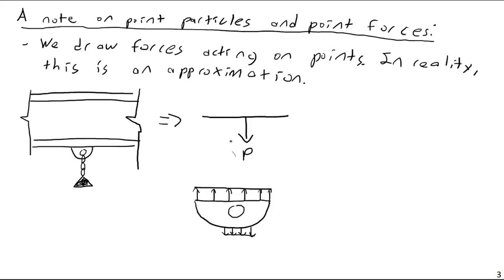So again, this is just a model. It's a useful model. Point loads are fine. Point objects actually work just fine for many applications. But I do want to just mention that in general, yes, this is all just models. So one question I often like to ask in my exams, sometimes I include a free response section, and I'll ask things like, can a true point load exist? Why or why not? And in reality, a true point load can't exist. I can't apply a point load over a single point, otherwise the load would just go right through the thing.